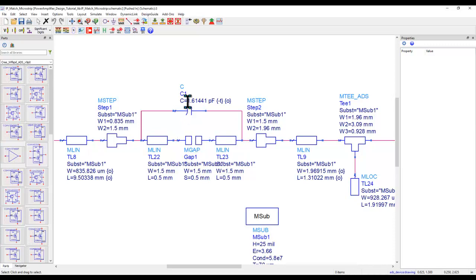And this I'm doing because I'm using a more idealistic model. But if you have more sophisticated models, like from Modelithics, they already include the effect of these pads. So probably your job will be a lot simpler. But again, those models don't come for free. They have to be purchased. So that's my way of doing pad parasitic calculation.